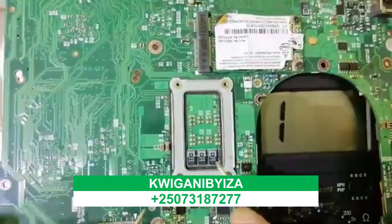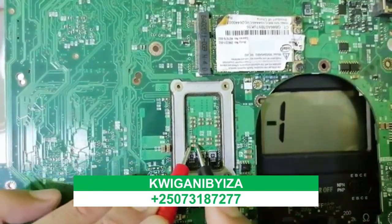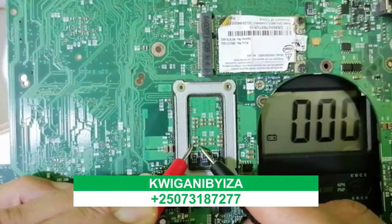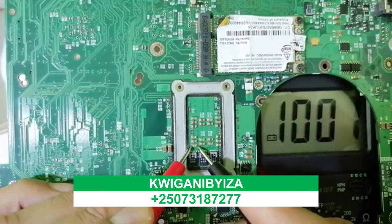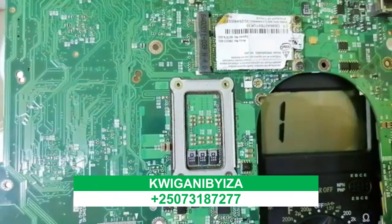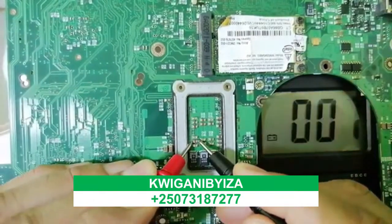The short is in the CPU circuit. So, the CPU is now installed. If I check these ceramic capacitors, as you can see, do you see? We have 0 in the multimeter. This is a short. Okay, let's check this one also. Do you see?